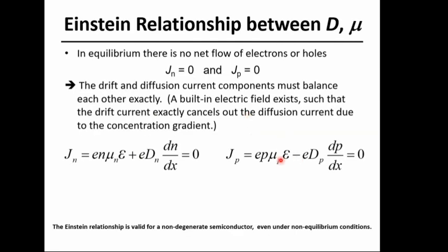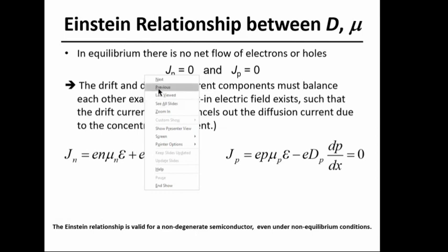Okay, so now I have a relationship between P and dP by dx and the electric field E. So I substitute, I will obtain kBT over the charge equal to dP over mu p, and the same thing, since for n I have minus, so the minus on this side will get rid of, and I will obtain the same equation.